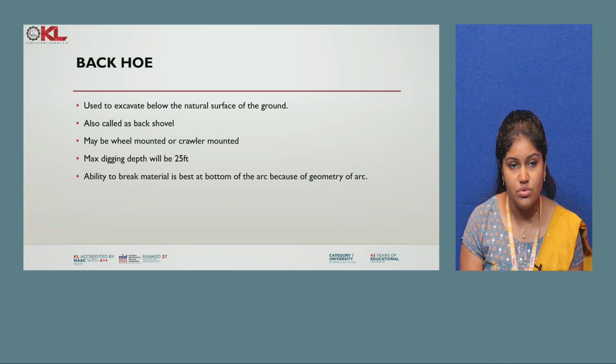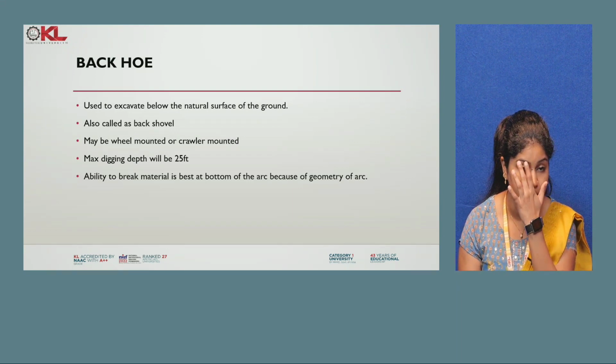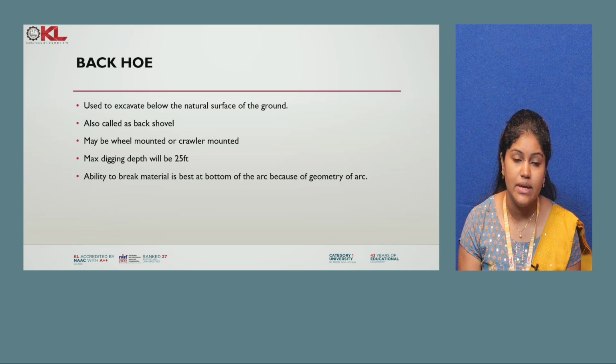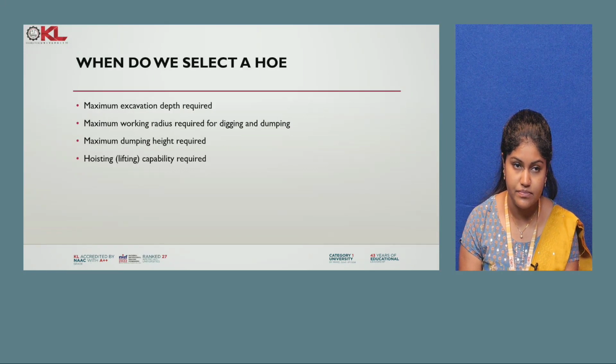It is used to excavate below the natural surface of the ground. It is also called a back shovel, and it can be mounted on wheels or on a crawler. The maximum digging depth will be 25 feet, and the ability to break material is best at the bottom of the arc because of the geometry of the arc.